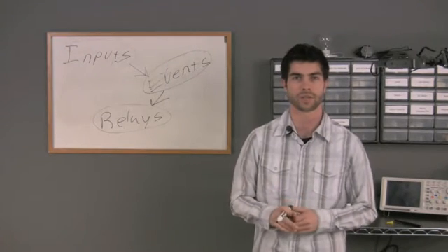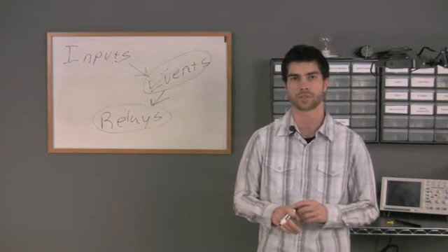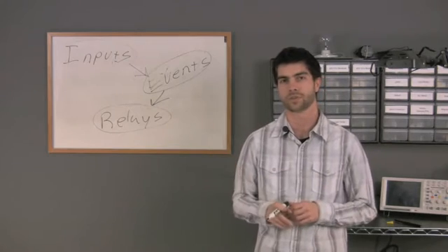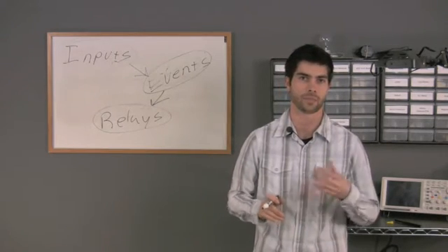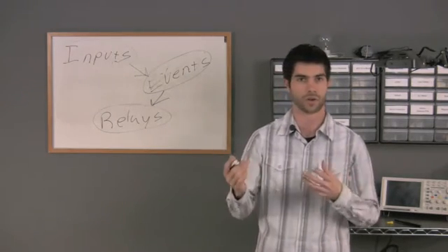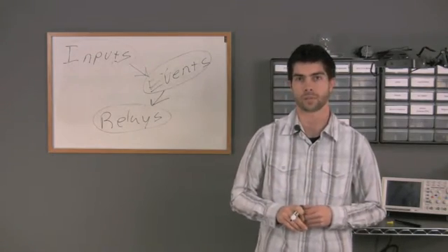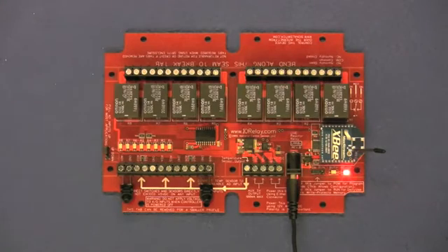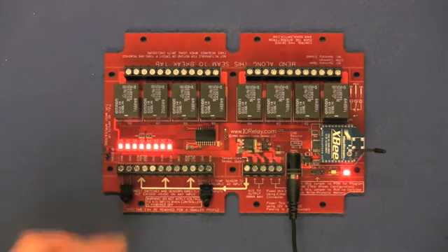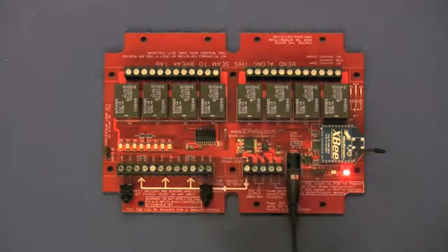So here's a little video clip of 8 timers being controlled by relays. You'll notice the relays come on for a specified amount of time and then they go off all in their own order depending on the time that was programmed into that particular timer. In this video, you'll see one input trigger 8 timers at once. The timers expire according to the configuration we loaded into the controller. So as they expire at different times, the relays go off at different times. Here you'll see a second button used to cancel all the timers.